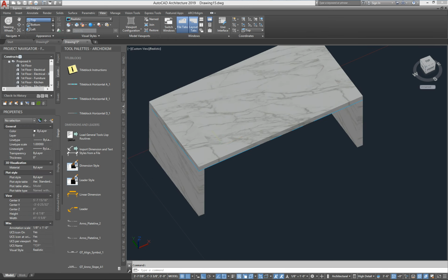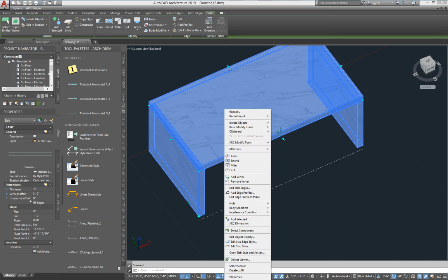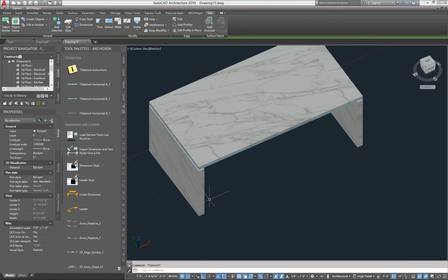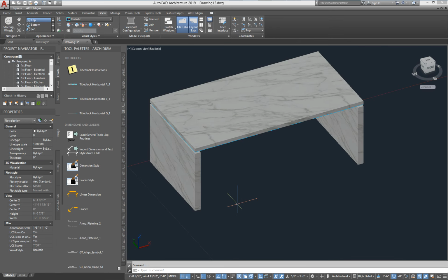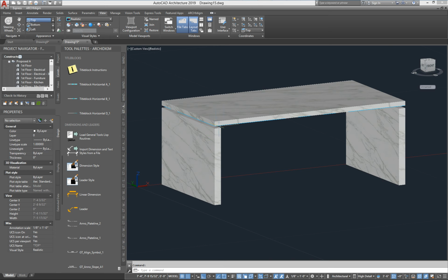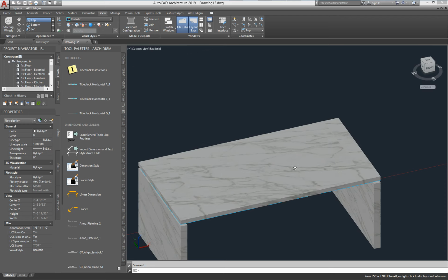It's a slab style, so it'll default to a 3-inch thickness. Now if you want something else, like say a 2-inch thickness, it is going to tweak it a little bit, and you'll notice the elevation height is 2.9, so for a 3-foot height, you're going to have to bump that up to 2.10, so it comes back up to the right height. And then you will notice there's a slight gap now because those edges were designed for a 3-inch thickness, but it's not a big deal.